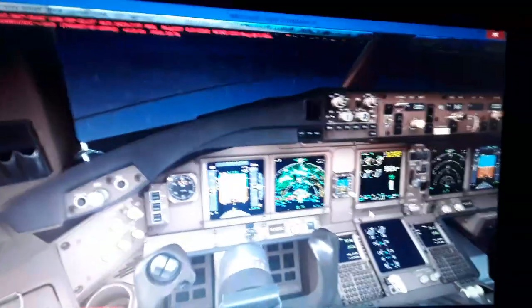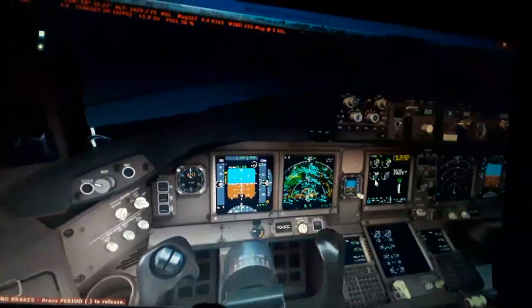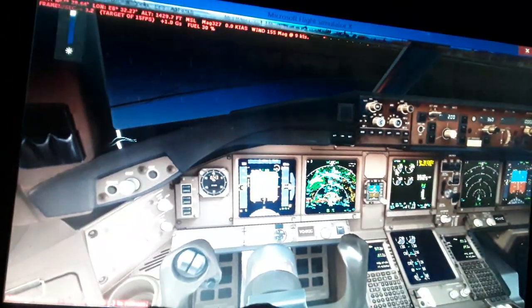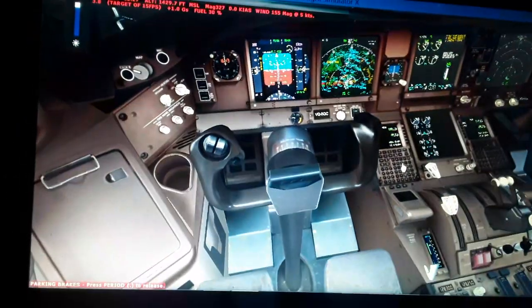So we have the transponder, ADS-B and ADC transmitter receiver that transmits and receives on our own frequencies and from other aircraft and generates all these warnings about the air traffic you can see in the navigation display. We have also the weather radar and with the terrain reflection, you can see. So we have the terrain and weather reflections over here in the navigation display.